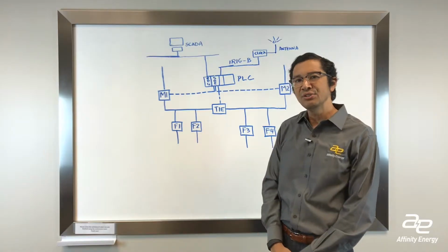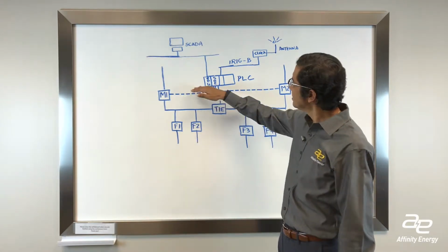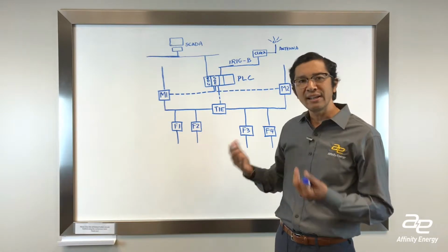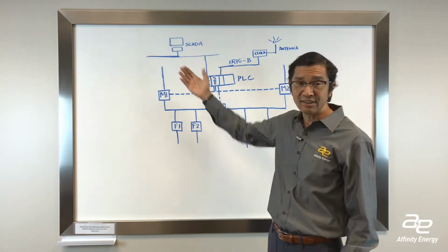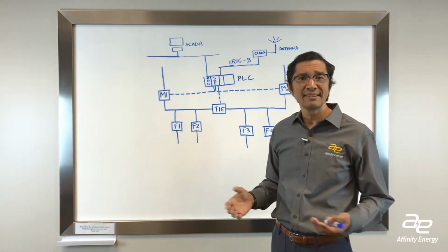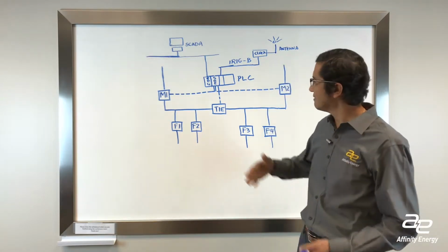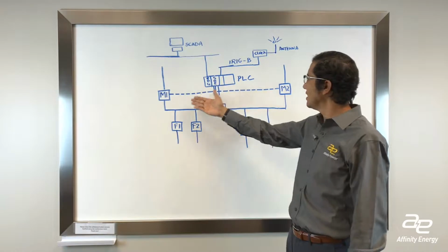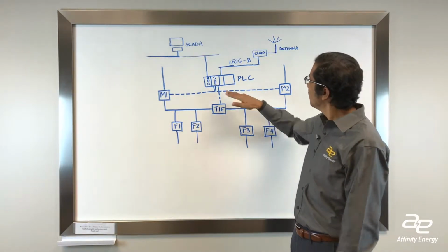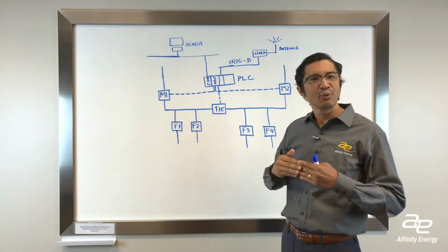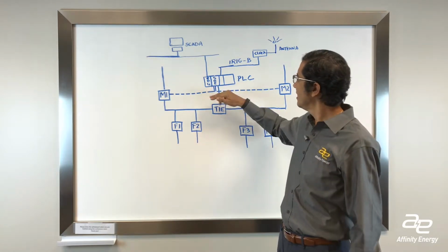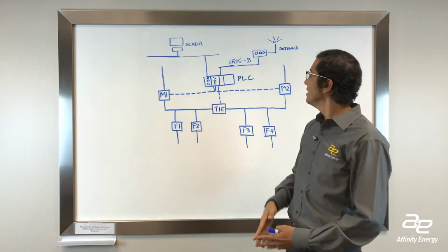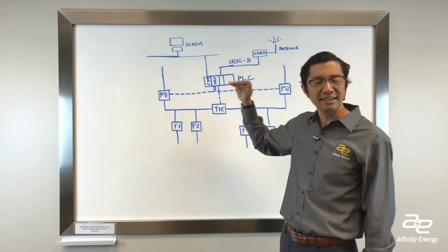It's important to, number one, make sure that any pieces of hardware that are reporting events to your SCADA system are on a common time base. And a common time base just means, for example, in this PLC, or even if it were a smart relay, we need to make sure that the clocks within all of these devices, and not only just the CPU, but there could be a redundant CPU, have a common time base.